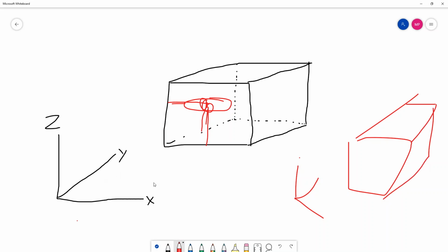If the origin is now, let's say, another inch in difference, that toolpath thinks it's supposed to be 1 inch above 0. If 1 inch above 0 is now shifted by 1 inch, this thing is now 2 inches above 0 because you've changed the reference point.